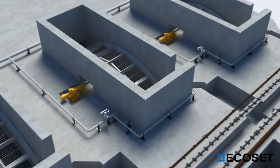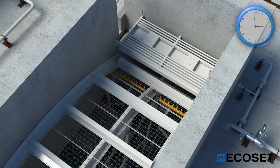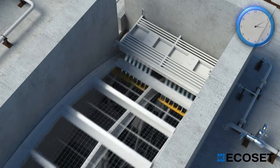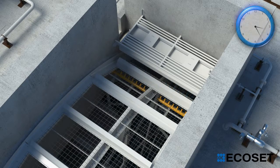Under the operating method of periodic time control, drum screen is operated once 7 hours and 40 minutes for 20 minutes, 3 times a day by the time sequence. The interval and running time can be adjusted in the settings menu. The initial startup method of drum screen for periodic time control is the same as that for differential level control.